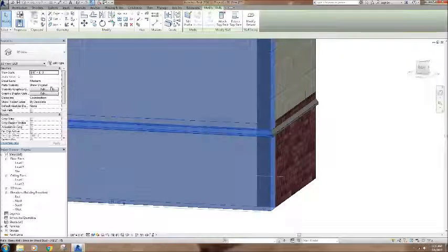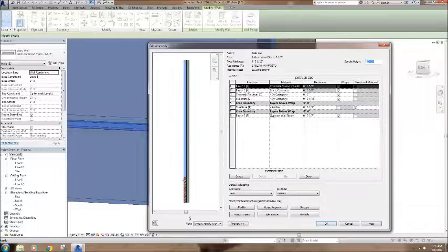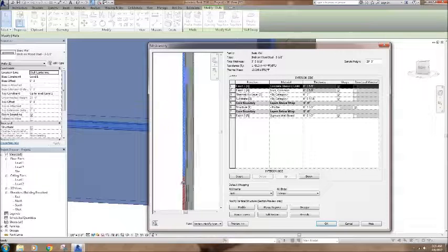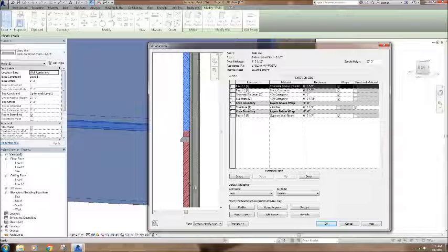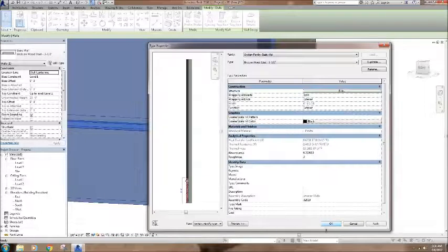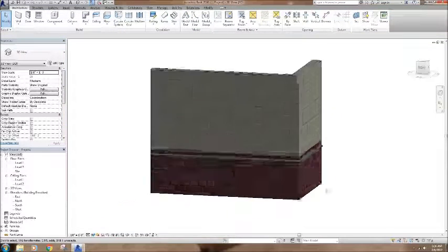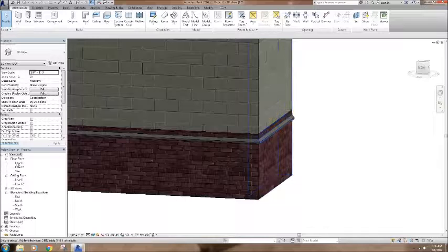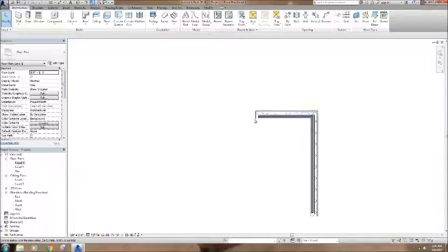So if we go back into this wall here, I cannot make this top one thicker than this one. If you want to do that, you're getting into a stacked wall rather than a compound wall, and I'll show you basically some of the issues with that. But another issue with doing these compound walls is that you don't very often end up with a perfectly flat site. It occurs, probably more so in commercial than in the residential sector.